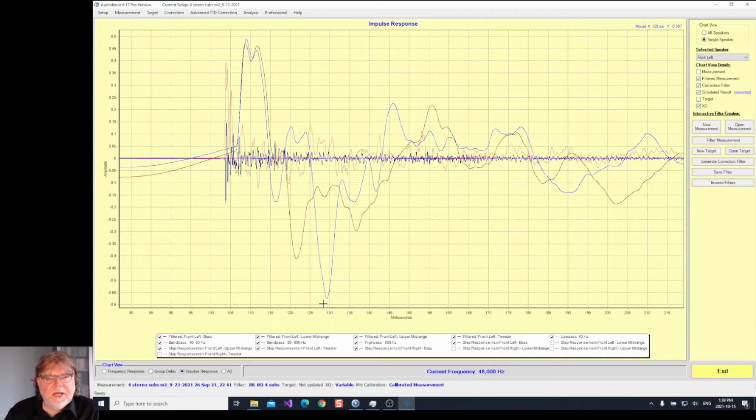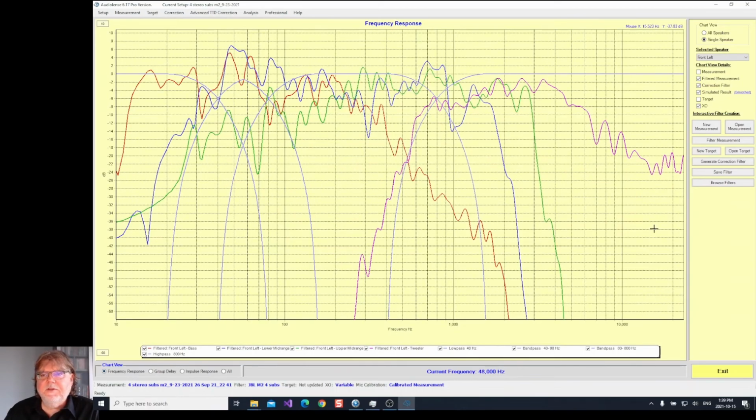So this is a great way to check to see that the measurements make sense. You want the left and right channels as lined up as best as possible. Audio Lens is going to time-align that when we get into that portion in detail. So if I go back to the frequency response of the one channel, the next step is, of course, once we've got our smooth responses, and again, just to help facilitate the conversation, at low frequencies it's the room and the loudspeaker that is getting into the measurement. And as we move up in frequency through the diffusion zone around 600 hertz, now we're looking at the direct sound of the M2 waveguide.